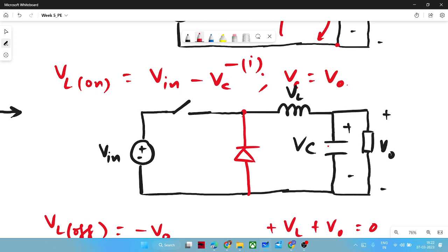That's what I am trying to explain in other words. Where is the question of the diode turning on here? The negative part of the potential should be there, no? I don't think there is a question of turning the diode on or off. But without the diode turning on, you cannot show the freewheeling action here. Where is the stored energy of the inductor going to be dissipated without turning on the diode? That is the question, right?